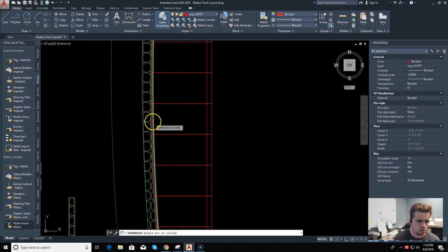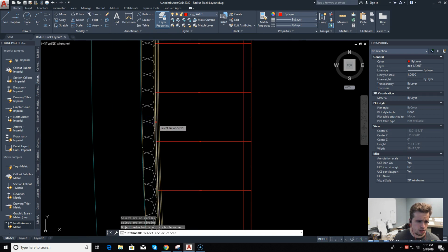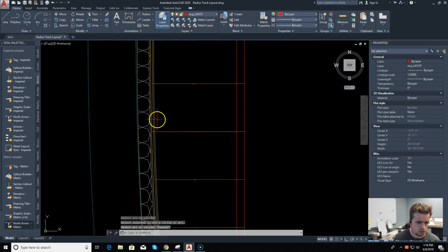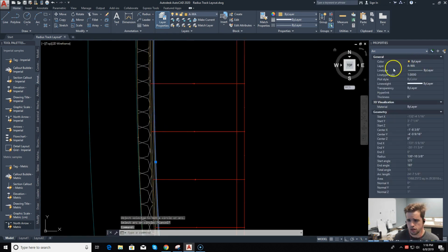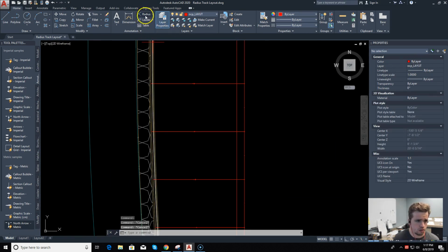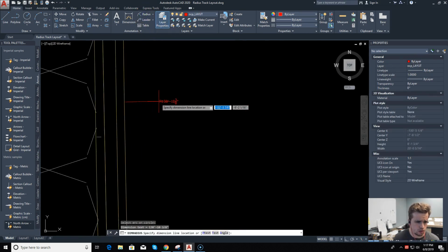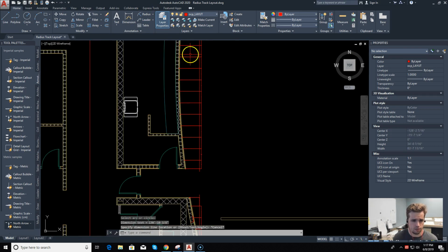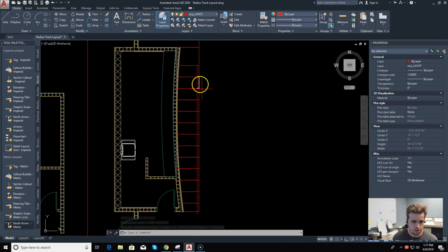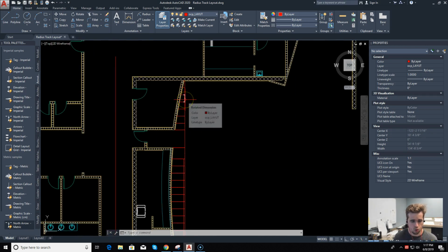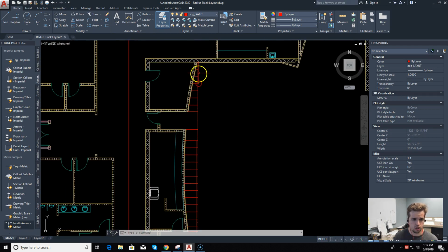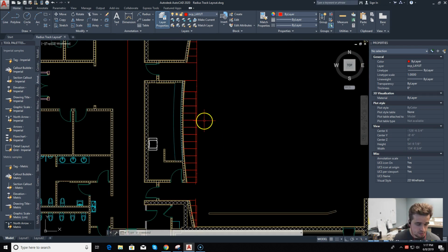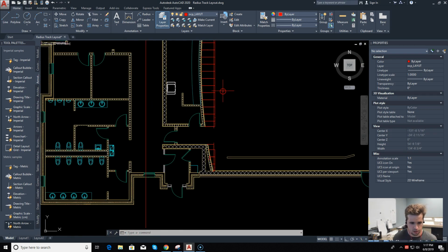So if I were to pull a radius of these walls, that's weird. These are just, that's an arc. Let's see here. So that's a 130 foot radius. Like, we can't swing that. So for us to make stuff, you draw a chord, and then you go every 2 foot and dimension it. So that being said, let's turn on some jams and let's get to work.